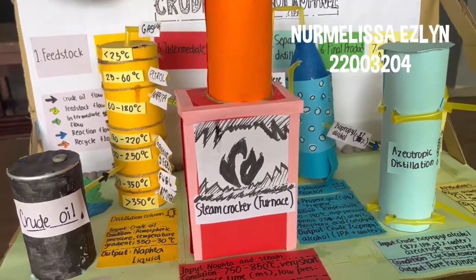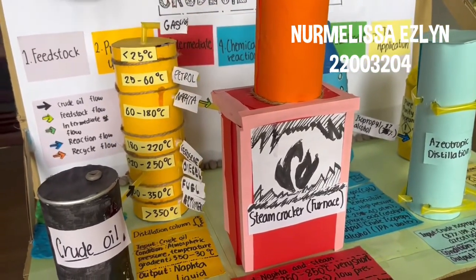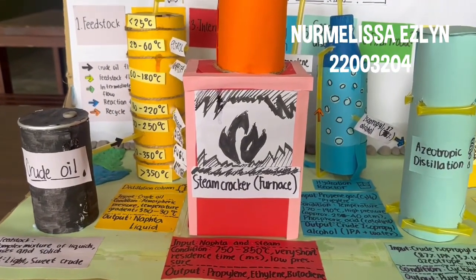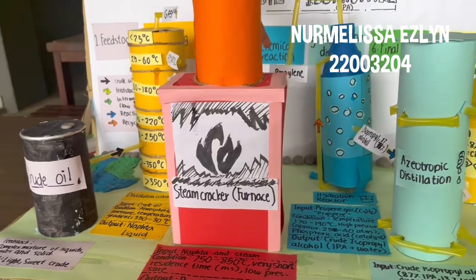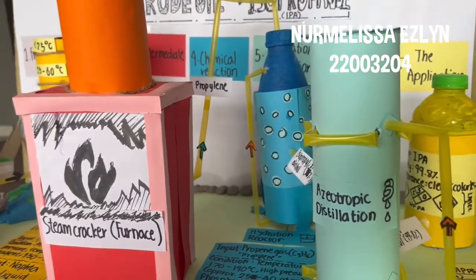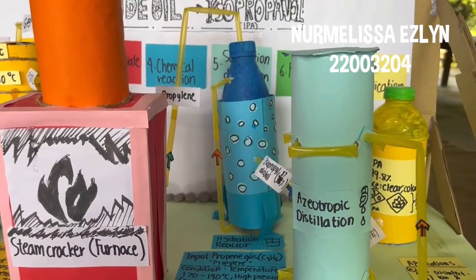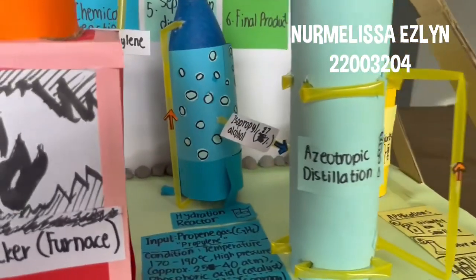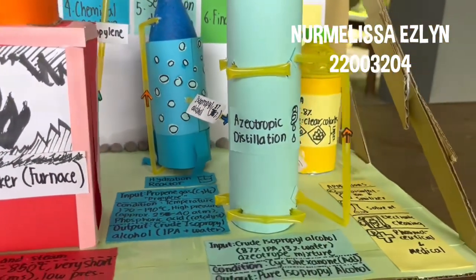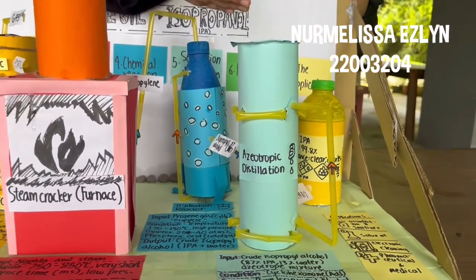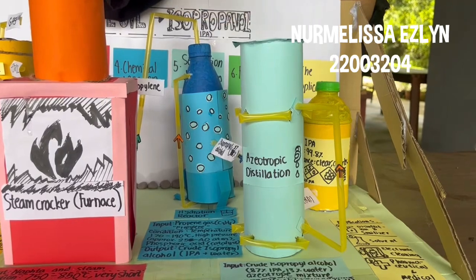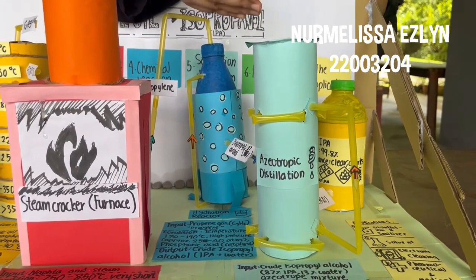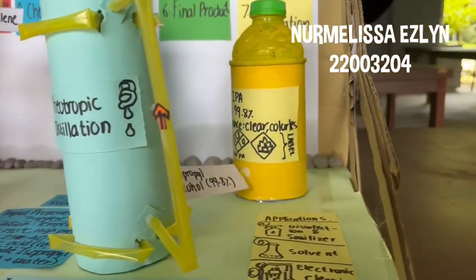The naphtha enters the steam cracking unit. In this unit, a very high temperature is used to break the hydrocarbons into smaller molecules, mainly propylene gas. Then the propylene reacts with the water in the hydration reactor under a high temperature and pressure in the presence of phosphoric acid catalyst to produce crude isopropyl alcohol. Then, lastly, the crude isopropyl alcohol undergoes purification using azeotropic distillation to remove the water and impurities, producing a high purity isopropanol suitable for medical, electronic and sanitizing applications.